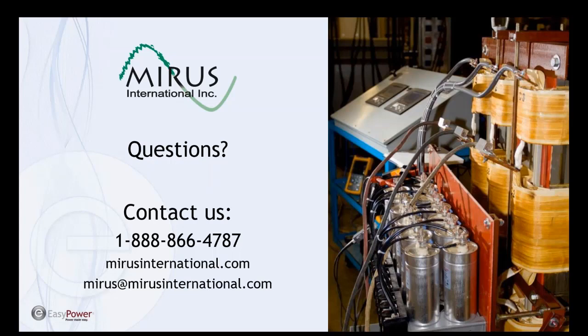But what happens with active front ends is the active front end has an IGBT input bridge instead of a simple rectifier input bridge. Those IGBTs switch, and when they switch, they introduce switching harmonics. These switching harmonics are high frequency, and they inject these harmonics back into the power system.